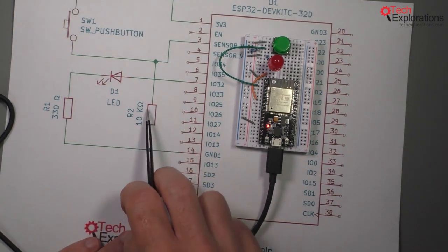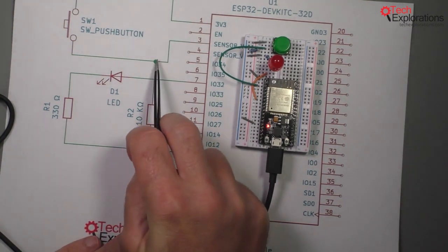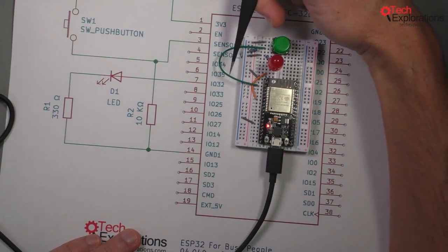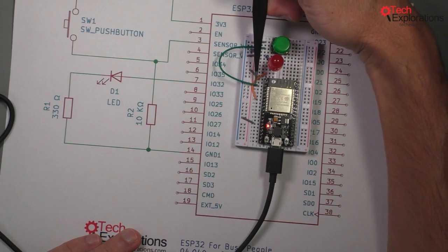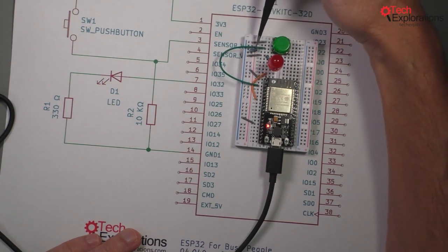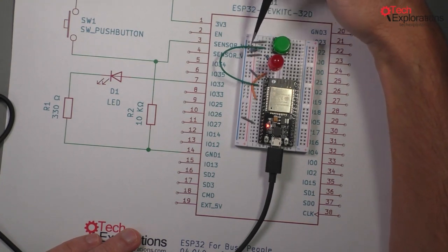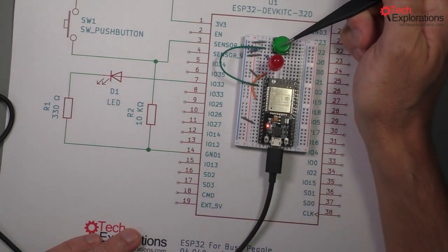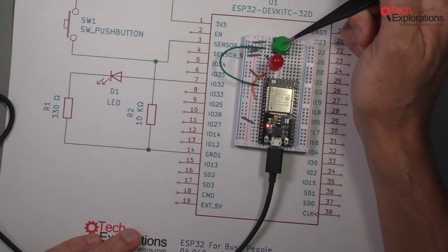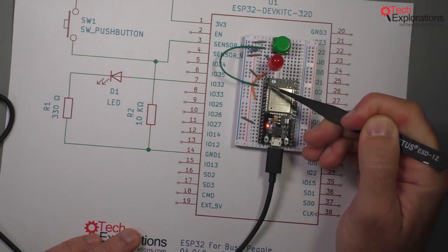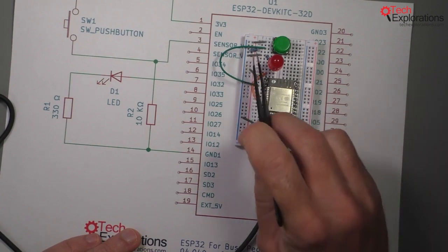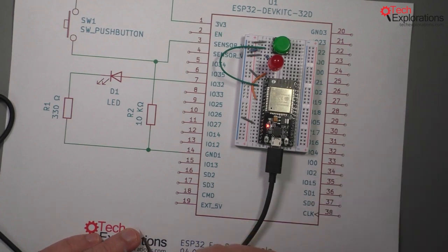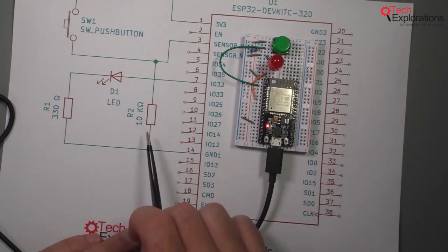I also have used a 10 kilo ohm pull down resistor because pin number 1 is the one that I'm using to take the reading from the button to the ESP32, and then I'm pulling this pin down to the ground pin, which is this pin right here, ground rail, so that when the button is not pressed, it's just floating, the ESP32 can get a definite ground level reading here, so that, as I said, the reading is not floating. So don't forget this pull down resistor.